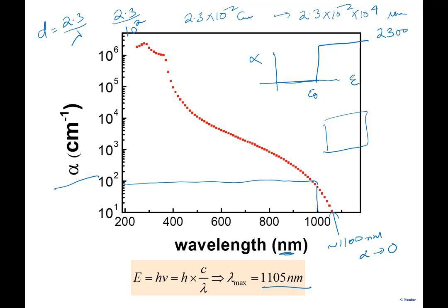What is the silicon wafer thickness itself? You can only make maybe 300 micron, 400 micron. That's a typical silicon wafer thickness. So even though it is theoretically possible for silicon to absorb everything up to 1100 nanometer, you need very thick silicon, because the absorption coefficient is very, very low.